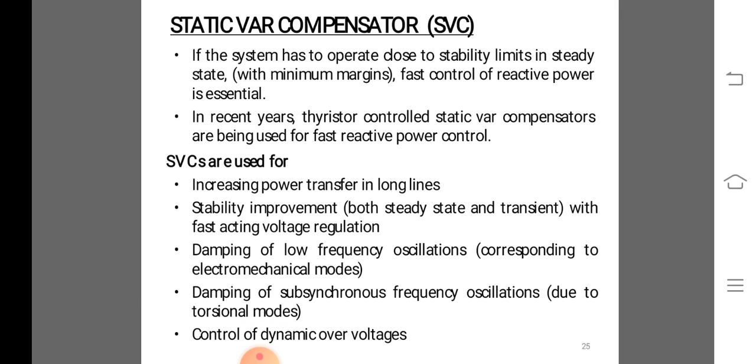a VAR compensating system. Some possible configurations are mentioned, where the capacitor and reactor are connected to the low voltage side of a step down transformer. The capacitor bank may be distributed between high and low voltage buses.